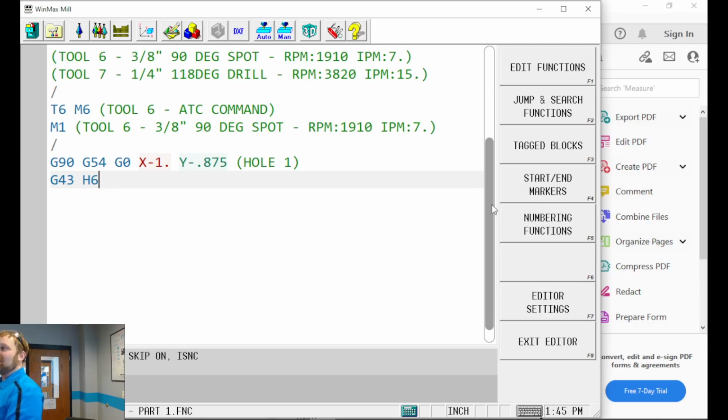So when I went out there to run the thing, it got to the finish pass, everything was roughed, looked good, all I had to do was finish, and it got there and it went because it was 0. So it tried to go through the part with an inserted face mill. Yeah, so H and T agreement, try to make sure you keep those matching, okay?